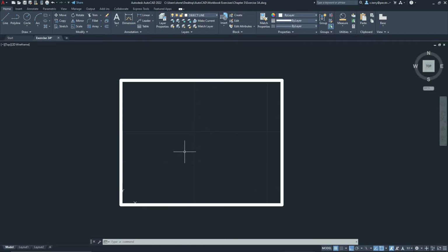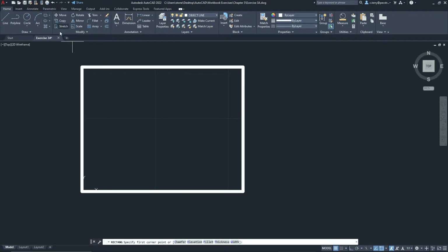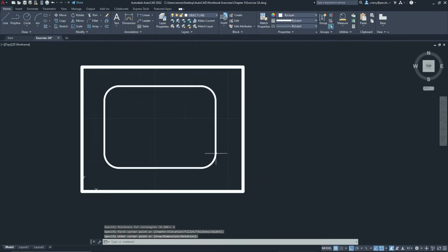Okay, I'm back. Sorry about that, guys. I'm not familiar with the thickness command being what it is. I was confusing it with the width command, which is an additional one. But essentially, when you click your rectangle command and you come down here for thickness, and let's say that I want it to be 2, when I draw this, I was thinking that it does what the width command does, which changes the width of the actual rectangle.